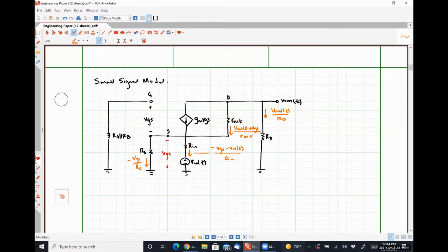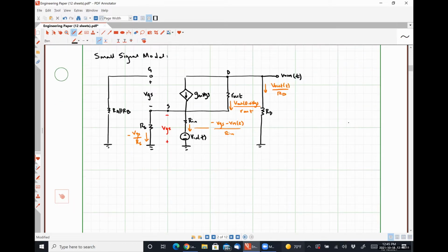And so I need to figure out how I can express all of my currents flowing through my resistors. So it's always the node where the current started at minus the node where the current lines up divided by the resistor value. And unfortunately, we wind up with a bunch of negative signs in weird places based on the polarity of that voltage VGS. So if we apply KCL at our output node or our drain node, because they're the same thing,